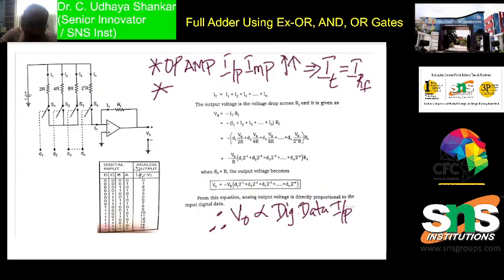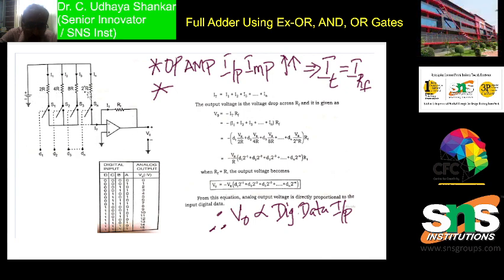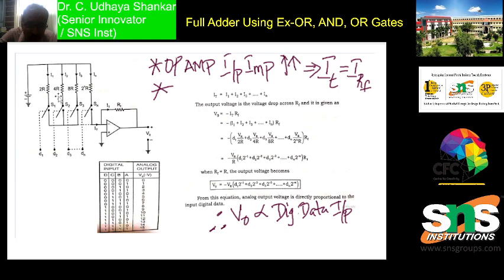Here let us go into the circuit diagram. This is the Vref which is given over here, and the op amp is having 2R, 4R, 8R and similarly 2 power n R. According to the value of resistance, the current flow will be varied.